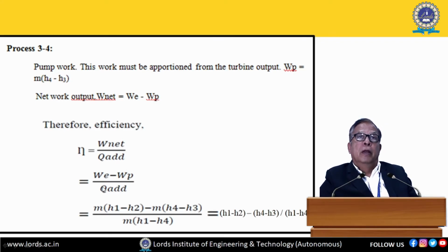Then the cycle which I have shown was with the steam in a dry saturated condition. Now here this is the Rankine cycle with superheated steam. I have explained the TS diagram. The point is going beyond this dome, so that means the condition of the steam here is superheated. So when we supply superheated steam, the work output increases, so the efficiency of the cycle increases.